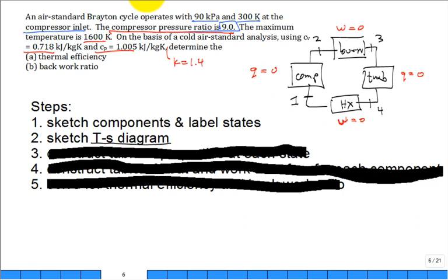All right, so maybe when we come in here and we draw this dashed line, what is the professor doing? And they put a little CV, control volume analysis for that compressor. You know what? We're shifting. When you did Otto and diesel cycle, it was a closed system analysis of a trapped amount of air in a piston cylinder undergoing processes. This is open, not closed. And we have inlet flowing across the boundary of the control volume and outlet flowing across the boundary of the control volume. It's all steady state, and we're going to neglect changes in kinetic and potential energy.